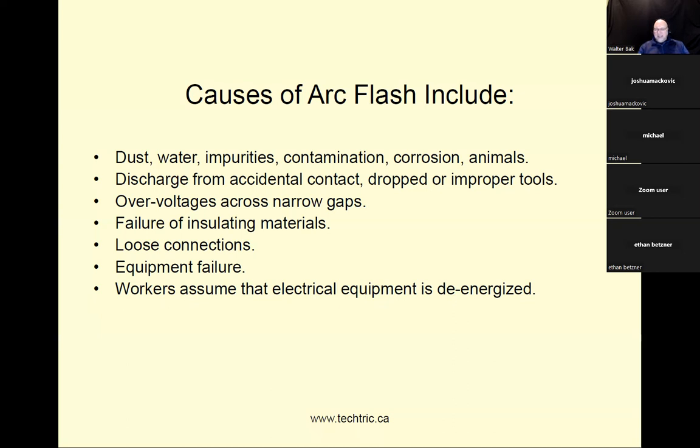And from one company to another, the procedures may vary, but there are some things called lockouts or tag outs. A lockout is a specific mechanical device that is put on a disconnected piece of equipment in such a way that it has to be unlocked in order to be turned on. Right?